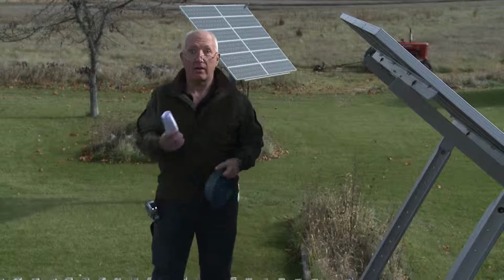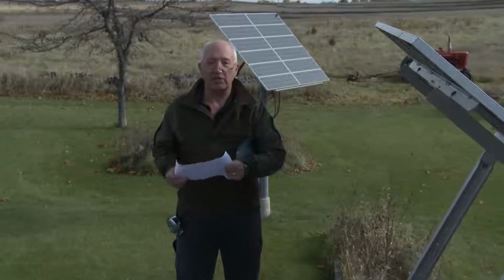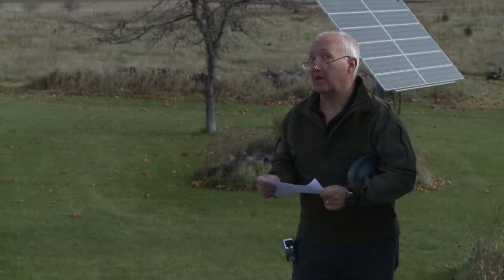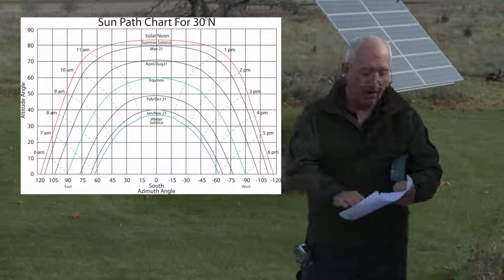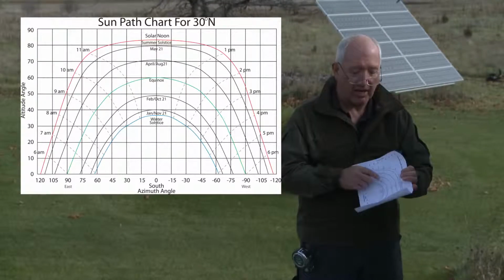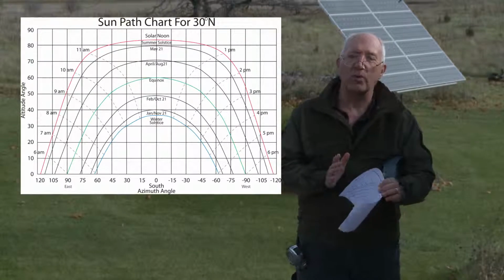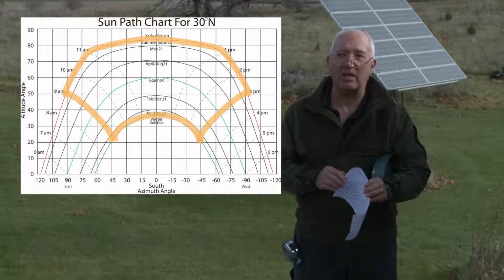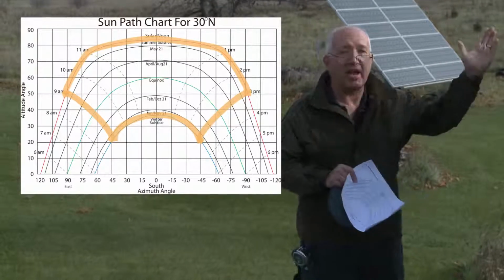Right here in my carpenter pants pocket, using the example from the NABCEP exam, I have a sun chart for 30 degrees north latitude. Do you see that up in the corner of the screen here? Now, what I want you to see is that there are times listed on here in somewhat vertical arcs. We have what's called the solar window from 9 a.m. to 3 p.m.